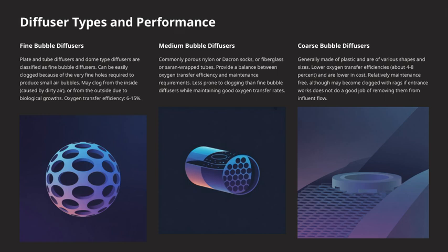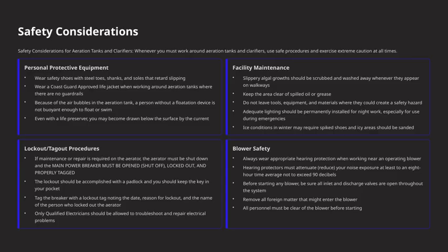maintenance, and cost. Let's talk about safety considerations when working around aeration tanks and clarifiers. First and foremost, always follow safe procedures and exercise extreme caution. These are critical areas, and safety should never be compromised. Personal protective equipment is vital. Wear safety shoes with steel toes, shanks, and slip-resistant soles to protect your feet.